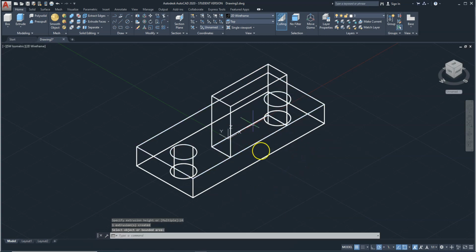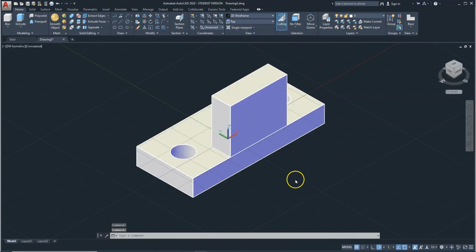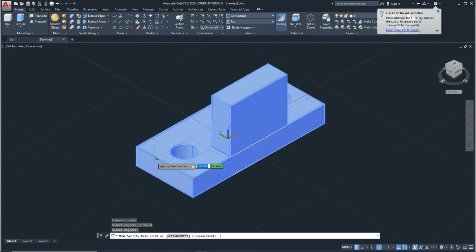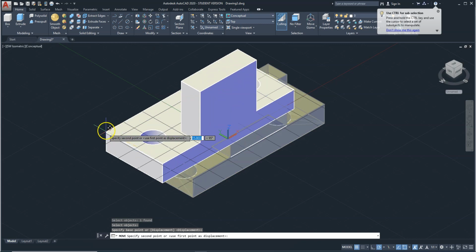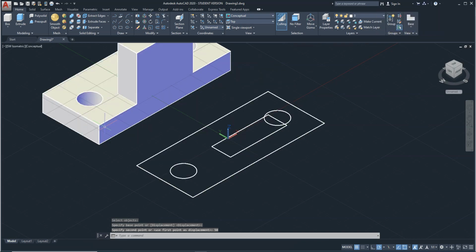Okay. And also, you know this, I have another one at the other side, but this time I want to show another difference of press pull. As you know, if you use extrude, the profile you used will be erased after the extrude operation. But this time, look at this. I want to move this solid model. I select this one. Maybe first we change it to conceptual, and now use the move. Select the model, enter, and move it to any direction. It is not important, for 50mm.